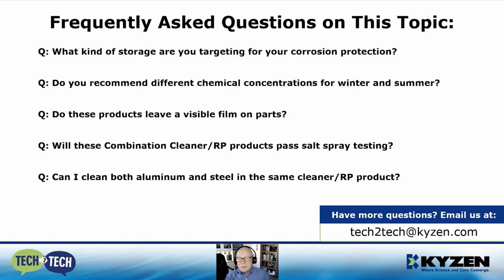So some frequently asked questions are in this last slide: what kind of storage are you targeting for your corrosion protection? What we target, we simulate storage inside a warehouse or inside a truck where rain's not actually raining on the parts, but you're in a very humid and hot environment. This could be the summertime in Michigan or Malaysia.